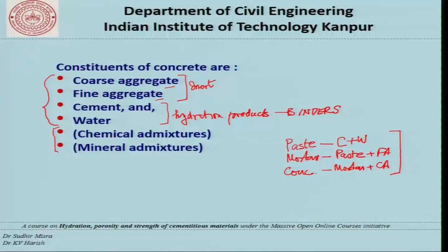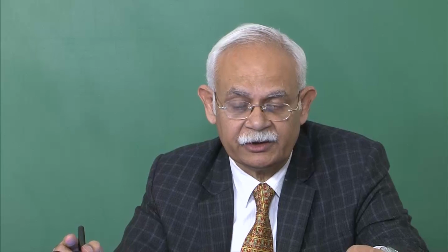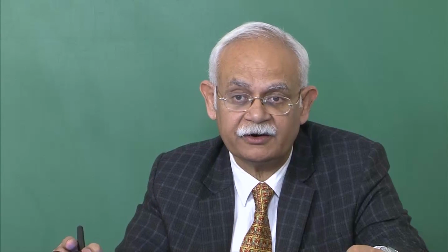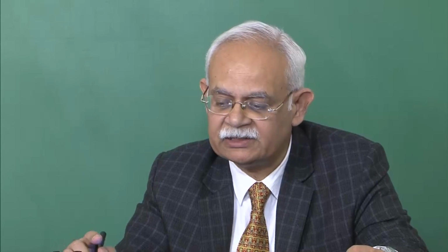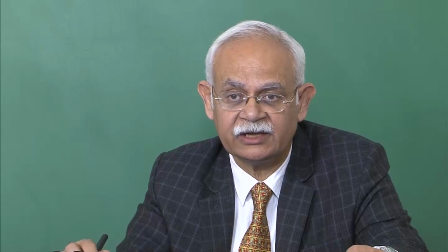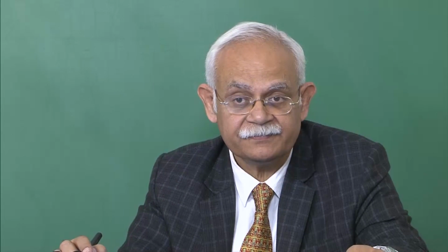So one way of looking at concrete is a suspension of coarse aggregate in mortar. Mortar is a suspension of fine aggregate in paste, and paste itself is a suspension of cement particles in water. We must remember that the fluid component or the liquid component of concrete is only water. Cement, fine aggregate, and coarse aggregate are all solids.